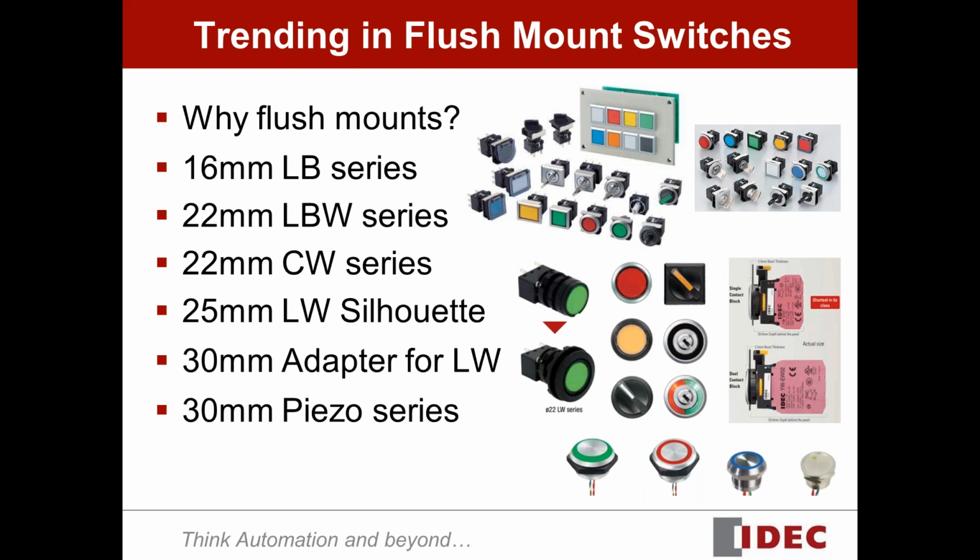The versions you see at the bottom corner are the 4 styles of piezo switches we have. Because they are completely sealed, they have IP ratings of 68 and 69K. So you can use them in very harsh environments that require power washdown applications.